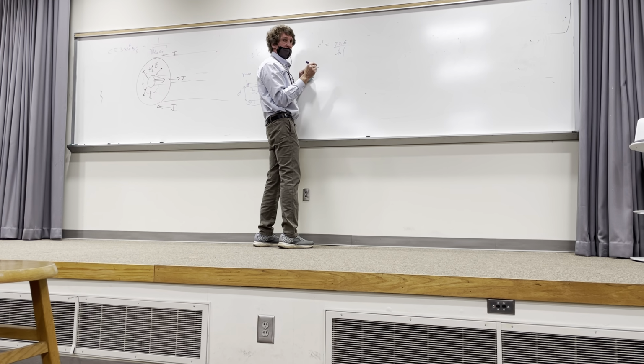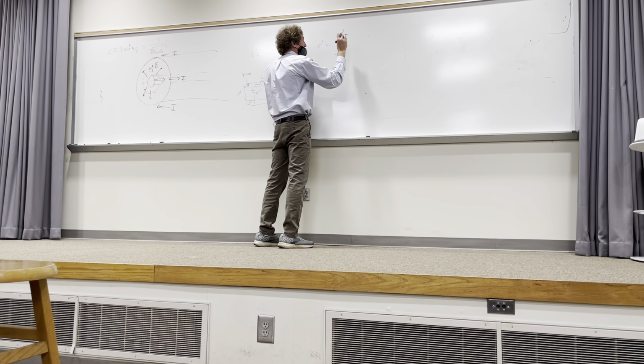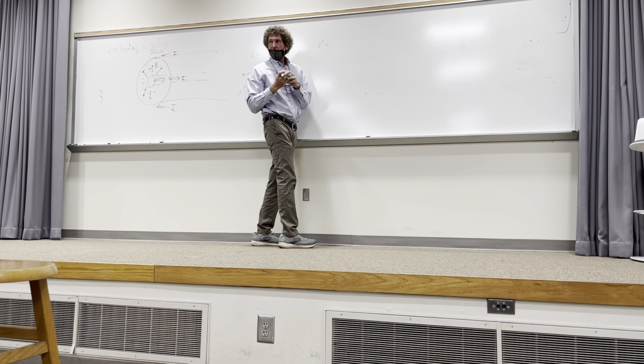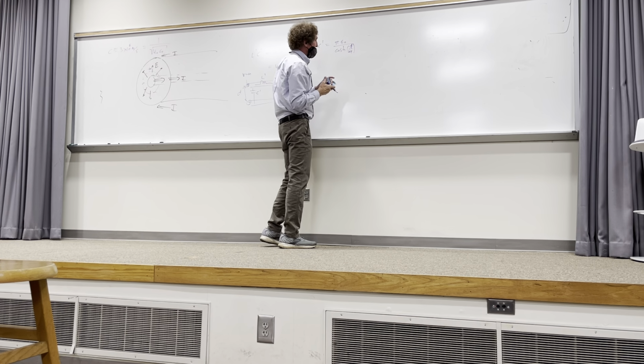Is B the separation distance? I think that's for coax. That's the coax cable, yeah. Oh, okay. Now this is twin lead. This is going to be pi, and I think it is pi epsilon up top. Inverse cosh. Yeah, it's the hyperbolic cosine. Cosh of, and then it's going to be separation distance D over 2A, isn't it? Over 2A. Okay, so that's diameter.